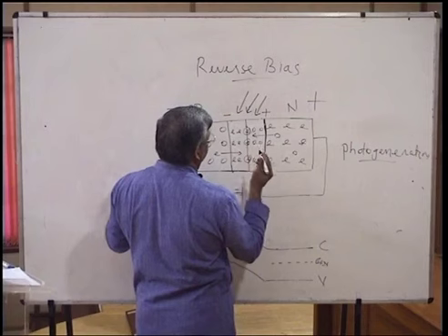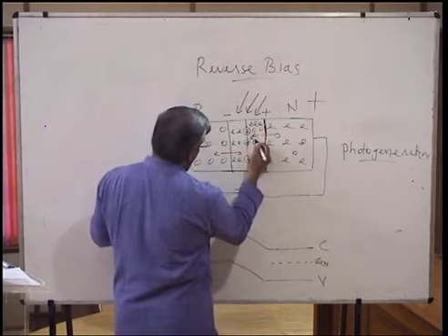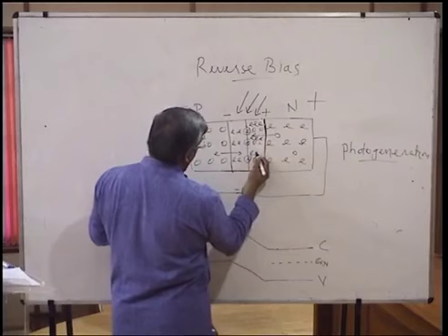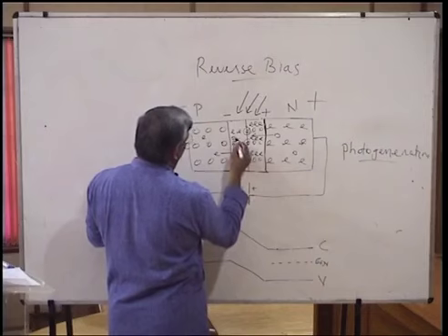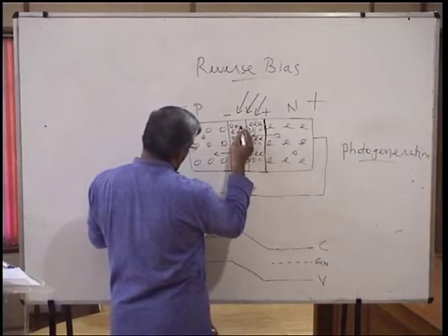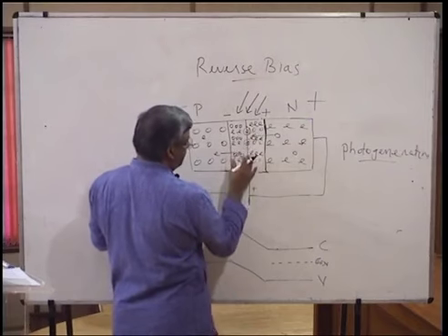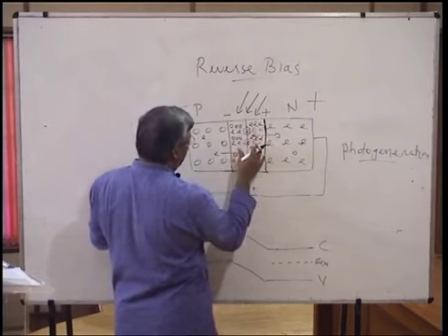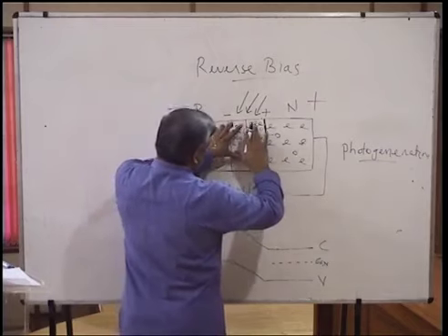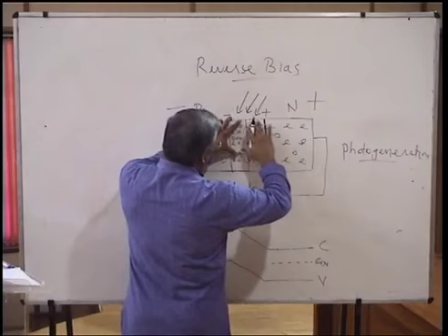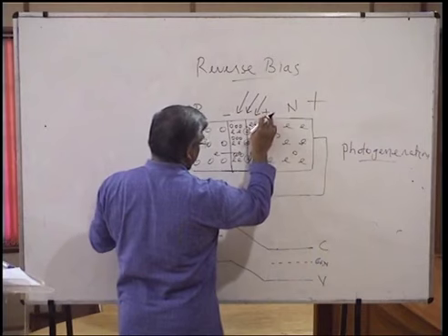So let's say electrons are created, large number of electrons according to the intensity of the light. In the depletion layer, they are created. Large number of holes. Actually, they are created together. Electron hole pairs are created. This generation of electron hole pair, but you know, there's a bias here. Because of the bias, the generated electron hole pair will be separated.